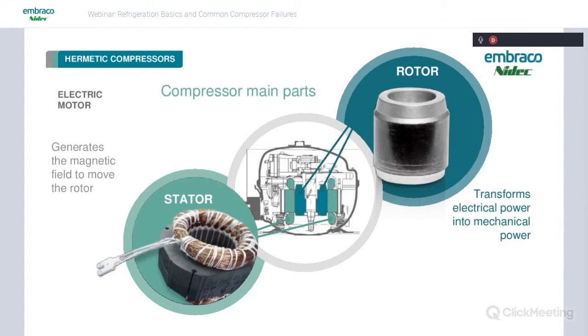In this slide, you can also see the crankshaft coming down into the lubricating oil. It has a little venturi opening in the bottom of it that, as it spins, draws oil up through the crankshaft and delivers it to the bearings of the reciprocating assembly.